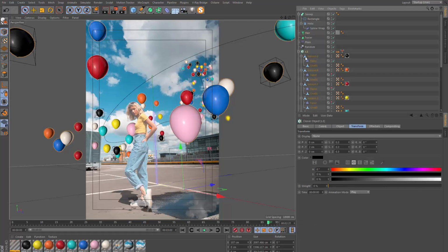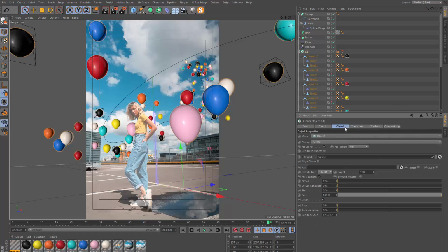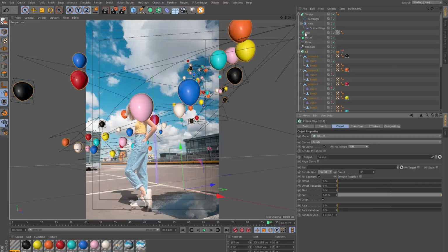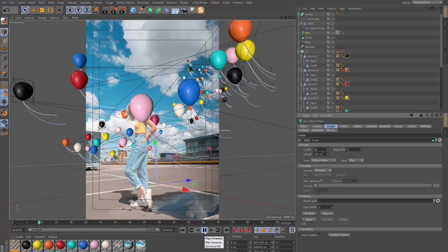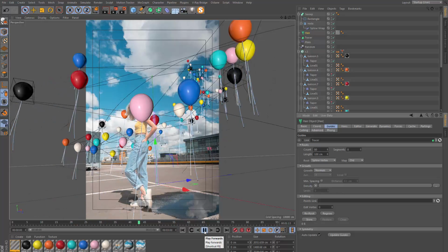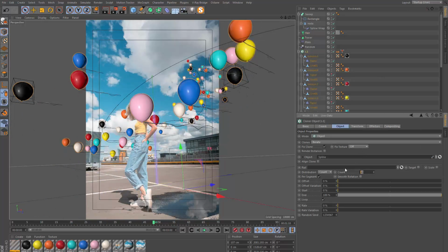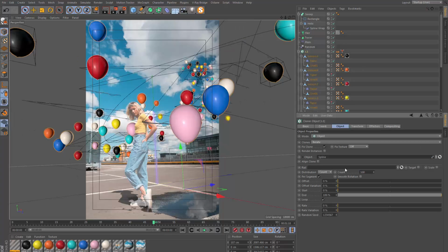because of the way this is set up, if you change the number of clones, for example, let's drop down to 80. If I go back into the hair, you're going to see the count of the roots has also dropped to 80. So this updates automatically when you change certain things. It's just that each time you do this, you have to go back to the hair and make sure you regrow and reroute your hairs so that they attach to the new positions. So it's quite simple and very procedural in the way that it's built.